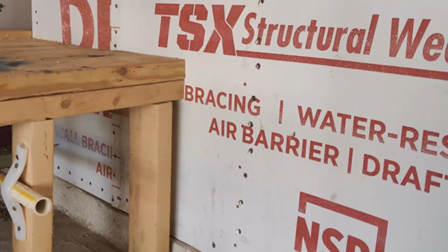Having this detail in the plans can ensure that a complete air barrier is on the garage side of the exterior wall. Notice I didn't say the garage wall. These walls, as we saw earlier when I added the term garage wall after exterior, from an energy standpoint should always be considered and treated as exterior walls. So from the thermal envelope's perspective, this wall is no different than any other exterior wall. It should not be treated differently.